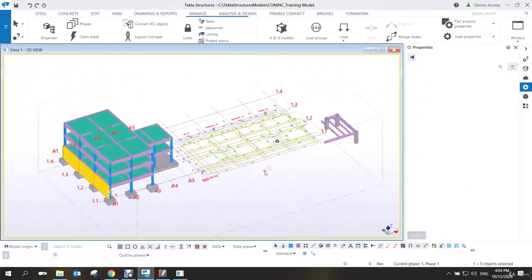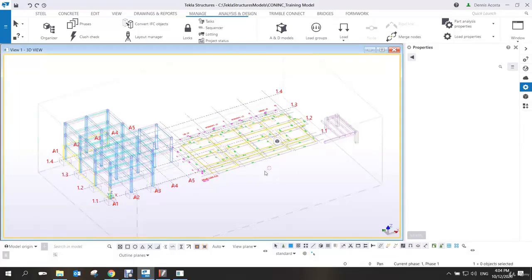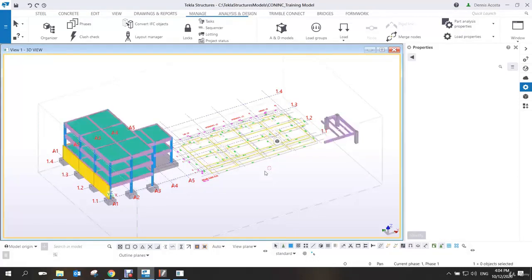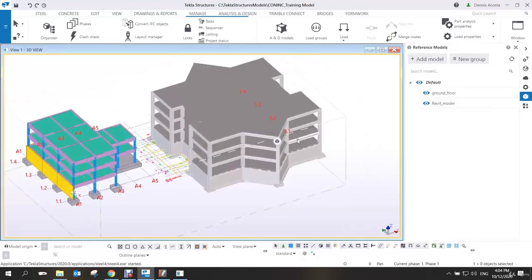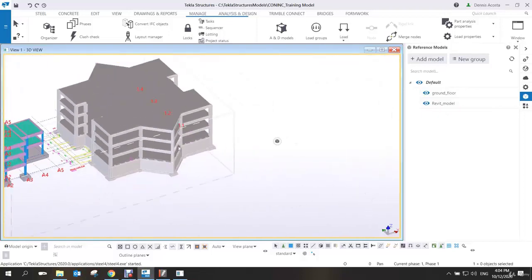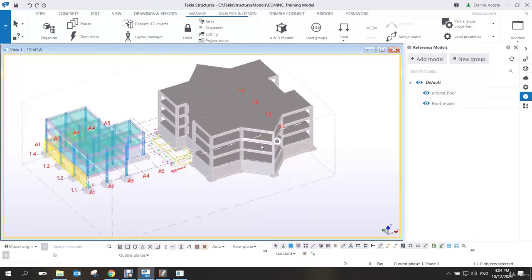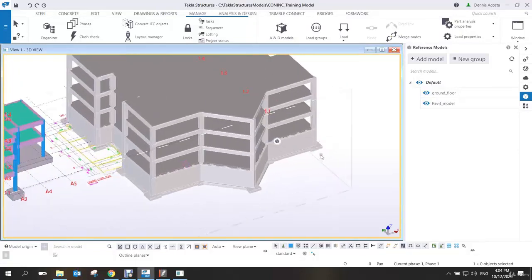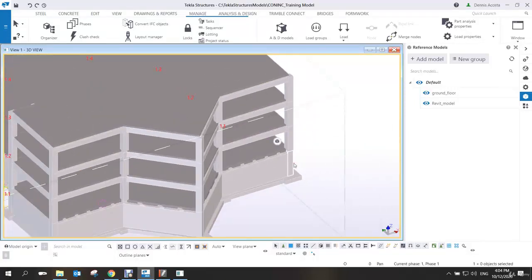Okay, look, can you look at this quickly? Remember, I have control 1, control 2, control 3, control 4, control 5, right? So let's say control 4. Now, if I turn on my Revit model, see, if I press control 1, the Revit doesn't change, right? Because this one is a component, so for the component it will be shift 1.